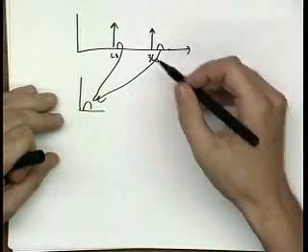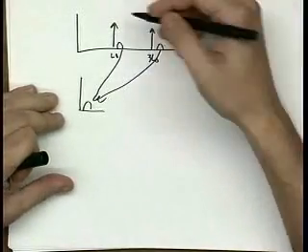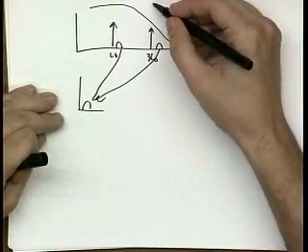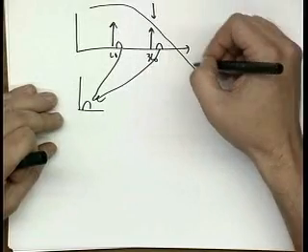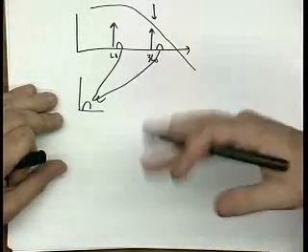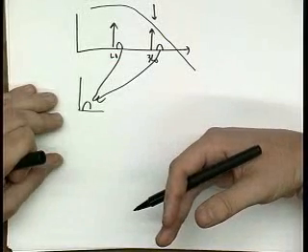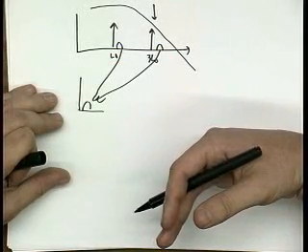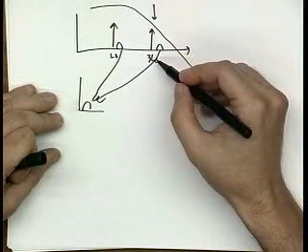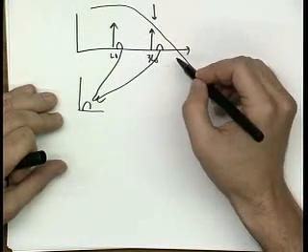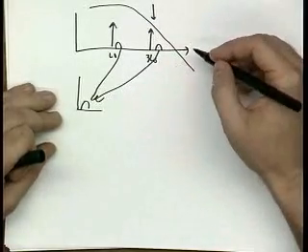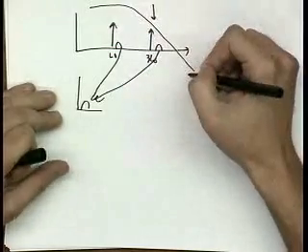The only thing you can do is add a filter. And so there is some filtering in here. There's a filter that looks sort of like that. So you're getting, like I was saying, sort of one pole with a suppression on each of these effects. Basically, the signals that are here, before they get mixed, have been suppressed by a filter. So we're suppressing the third LO and the fifth LO mixing terms. So there's almost nothing here to come down. In fact, because of the way the mixer works, there's actually two poles with the filtering.